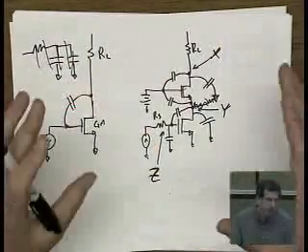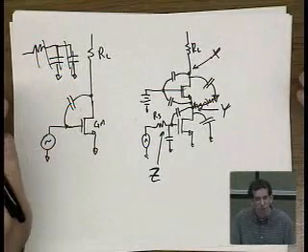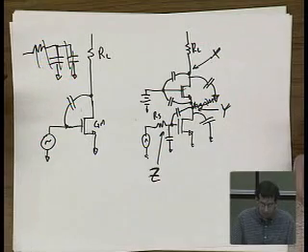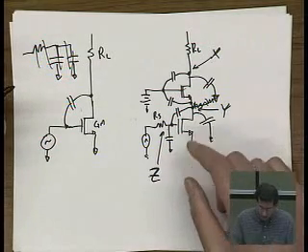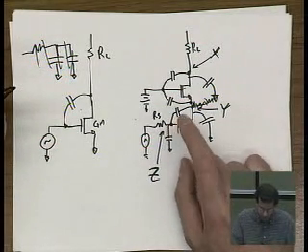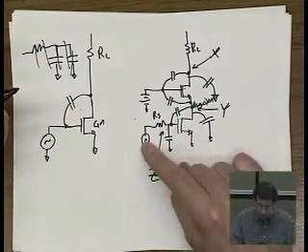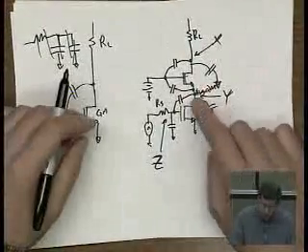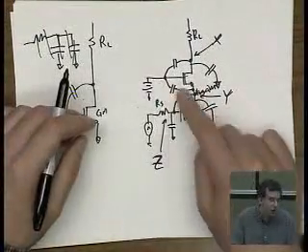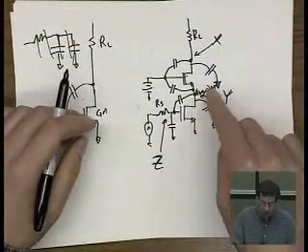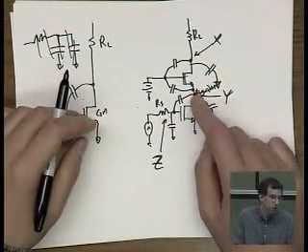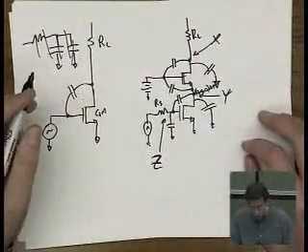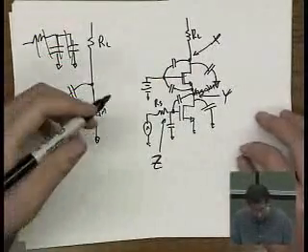Now, if you don't know the relative sizes of the capacitors, what's sometimes useful is to look at the relative sizes of the resistances at those nodes to ground. And what we know is that the resistance here is through RS, right? The resistance here is through RL. Those resistances might be appreciable. The resistance here is 1 over GM, okay? So this is probably going to be the highest frequency pole because all these capacitors will be on the same order. So, okay, let's look at the pole at node Z, okay?